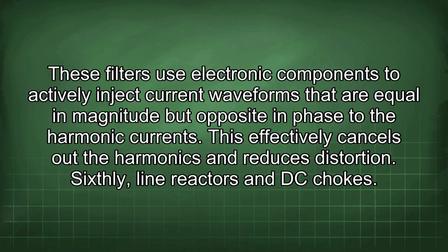These filters use electronic components to actively inject current waveforms that are equal in magnitude but opposite in phase to the harmonic currents. This effectively cancels out the harmonics and reduces distortion.